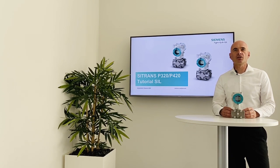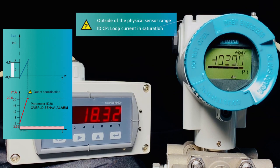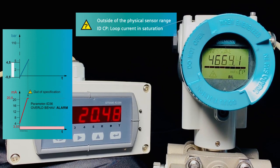In the following steps, we will change the pressure to cause a safety critical device error. I'm changing the pressure now. As soon as the current goes into the saturation, the symbol triangle with question mark for out of specification after NE 107 appears. Alternating with P1, info CP appears. CP stands for loop current in saturation. For this and more detailed information, refer to the chapter Diagnostic Messages in the manual.